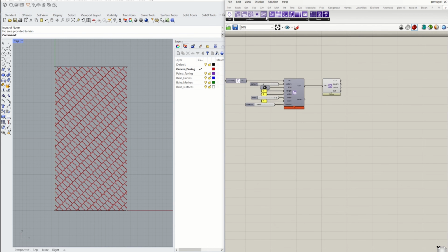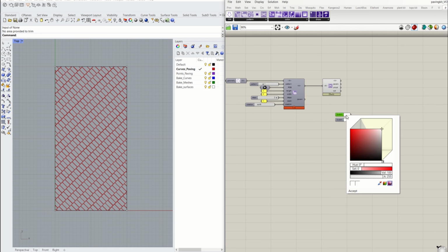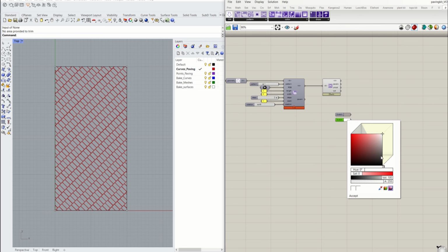Since this is an orientation video, we're just going to be using random pavement coloring. But if you want more control over the coloring, check out our campus videos to find out about our great color rule options, along with color mixes, custom paving input options, tessellation, and module arrays. We'll use a 2-color paving pattern for this example. Add 2 color swatches. Click on the colors and change the colors to what you want.